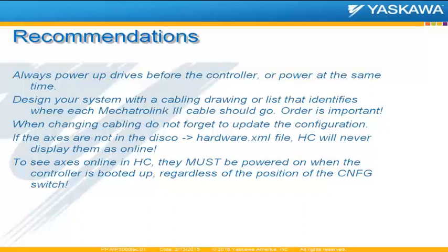When you're designing your system, especially if you're reproducing this, you should include a cabling drawing or a list so that you identify where each Mechatrolink 3 cable goes, because order is important. If you change the order of your cabling, that's going to change the value of your response times, possibly making it that you won't be able to find devices. When changing the cabling, don't forget to update the configuration.